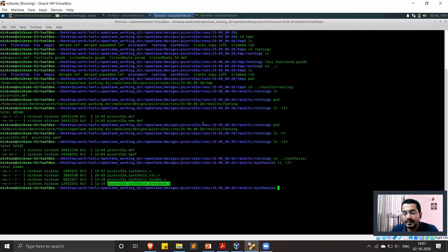First you focus on congestion, then you see if the congestion is apt or not. Then you move towards the timing, then you see if the timing is correct or not. And finally routing, followed by the DRC, where you clean any DRC errors. So right now in the design we have 3 DRC violations. When you experiment, you can use the TritonRoute strategy 14, that is setting the routing strategy as 14 and then running the route. So you will understand what I was actually referring to. It takes longer time, but it will ensure that your design converges. Converges means there are zero DRC errors.